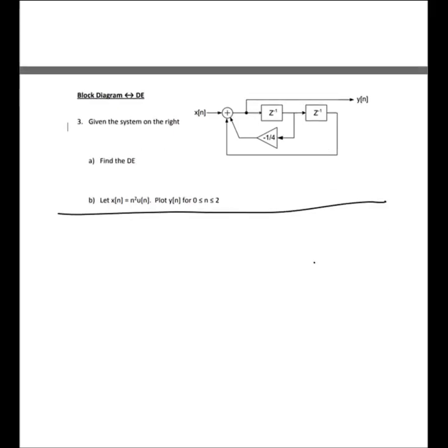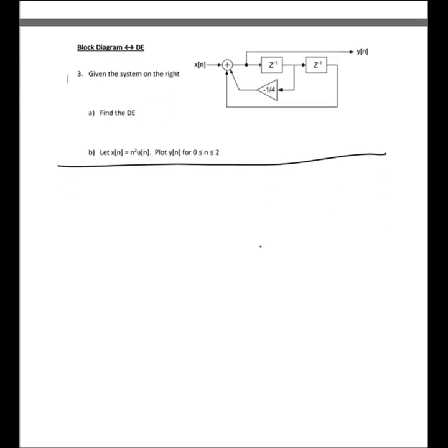So we're given this system, and we want to firstly find the difference equation giving this system. So Charles, does the difference equation depend upon what our particular input is? Do we need to know that our input is, say, this in order to find the difference equation? No, sir. Correct. Our difference equation just describes the system, so it should be completely independent of what a particular input or what its particular output is. So let's start off with a method to figure out how to do that.